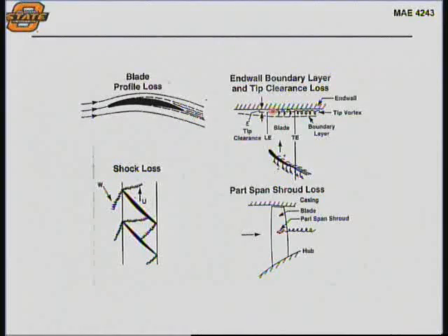So how big that clearance is going to be a key loss contribution. If you're moving supersonically, like at the top edges of either fans or some compressor blades, the relative velocity, W, could be supersonic. Hence, you'll have shocks and you'll have shock losses.